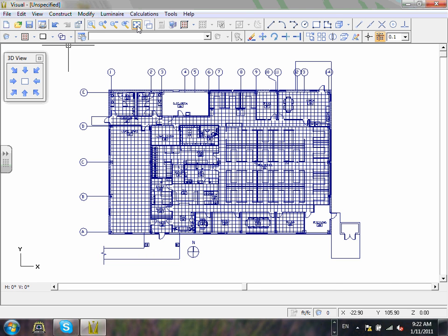Let's go Move. Pick them all up and right click. Here's the Move paste point for moving. This is the one that we're going to pick, this little paste point here. Now it's moving in my hand, right? I'm going to go back and put in 0,0,0. Enter. Now it should be centralized.